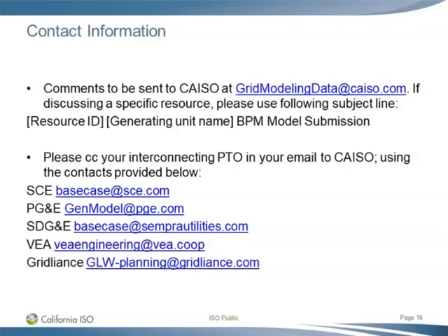For synchronous generators, they're only required to submit PSCAD models if they're located electrically close to series compensated lines, because in cases where these synchronous generators become radial from a series compensated line, there's a potential for subsynchronous interaction at frequencies below 60 hertz that can cause damage to the synchronous generator, actually damage to the shaft of the generator.